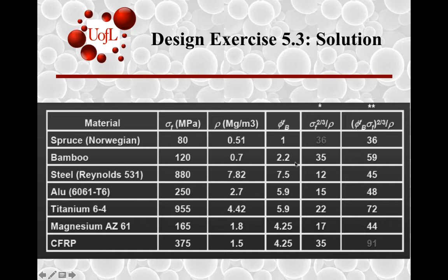If you begin to take into account shape efficiency factors to failure for these designs, you end up having much more attractive choices. Carbon fiber reinforced plastics in particular end up becoming the best choice, taking into account not only the fact that the efficiency factor is higher, but density is also not increased as much as it is for steel or titanium, for instance.